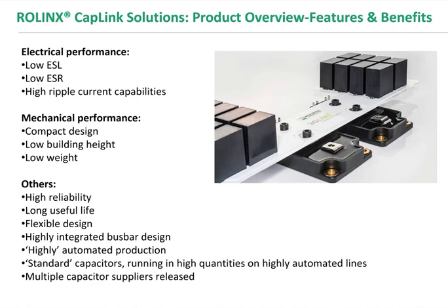I have not mentioned so far the name of the product, but it is called Rogers Coupling Solutions. We talked about inductance already. It is characterized by low equivalent series inductance and resistance, and we cannot forget about resistance, because it has an impact on the lifetime of the complete system. It is customized and very compact. We can make all kinds of configurations of capacitors on the busbars, a fully flexible design, and it is a highly integrated busbar design.